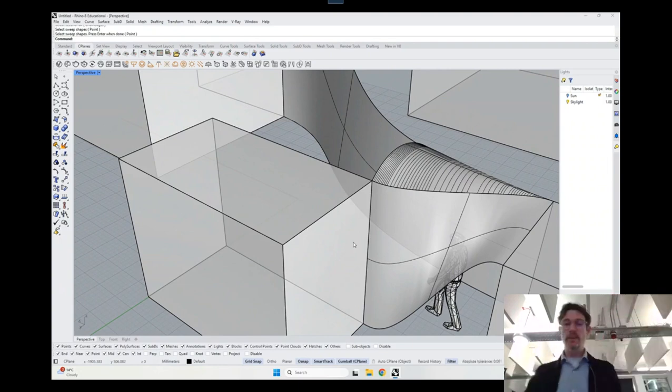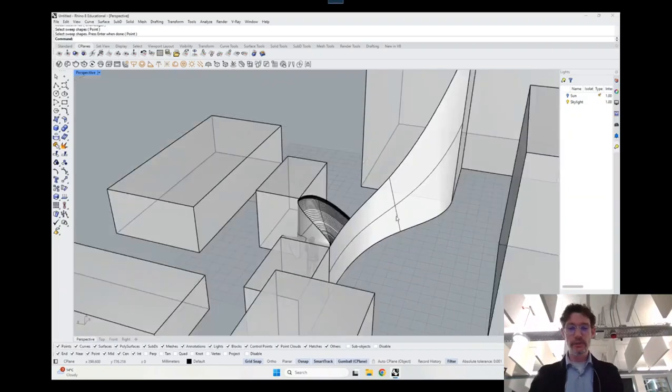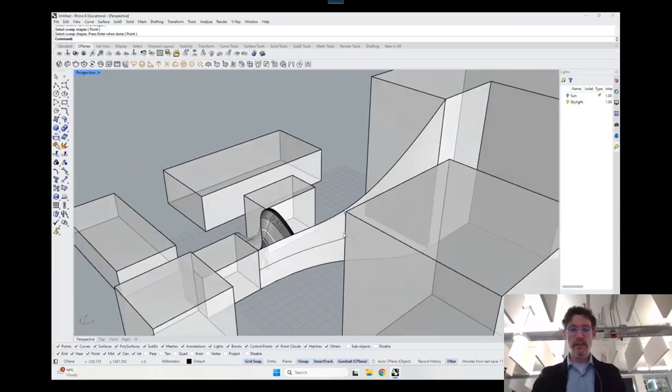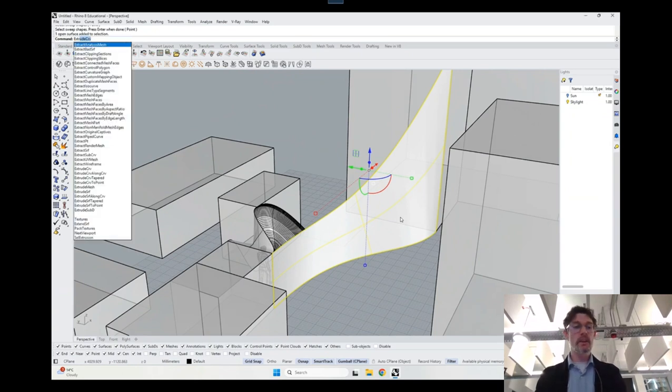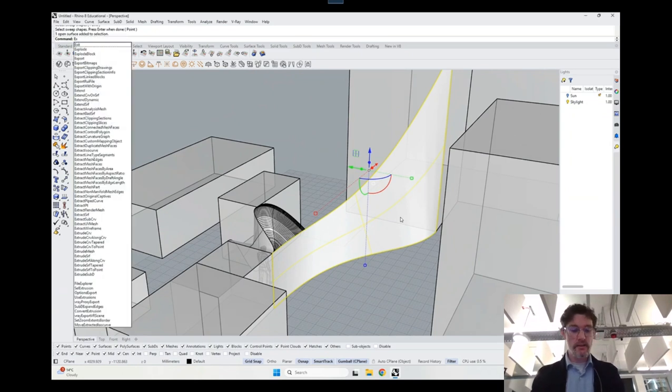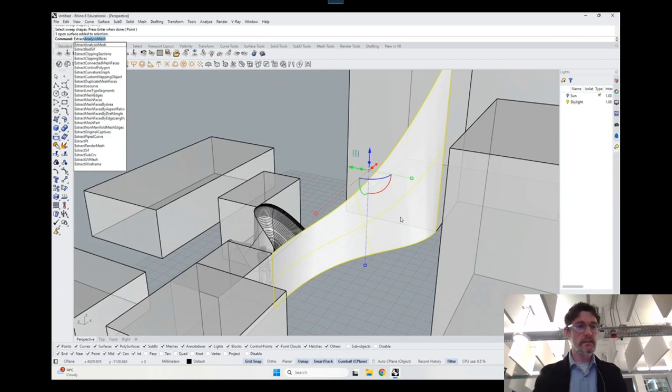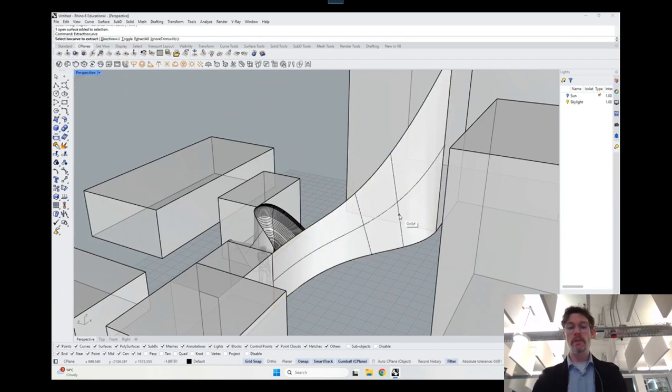And I could obviously keep going, and potentially also it might be interesting to think, well, I only did this shape between 2 curves. I could do what I did a couple of weeks ago and extract ISO curve. Remember that? I'm going to toggle this way, and maybe I'm going to take a couple of different ISO curves here.